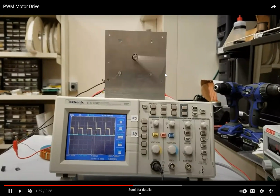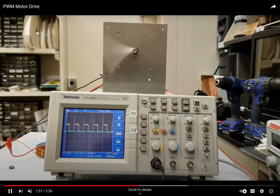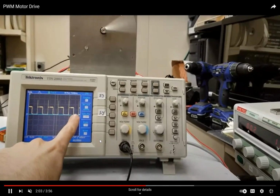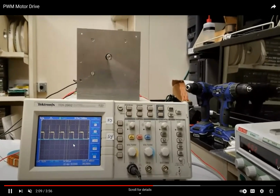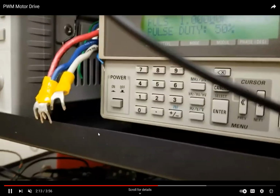So it's doing something called aliasing, but it's happening continuously now. What's going on is the motor is filtering out all of the AC terms. The motor is only responding to the DC term. Now, why do we do this? Because if I do it this way, my motor drive is essentially lossless.